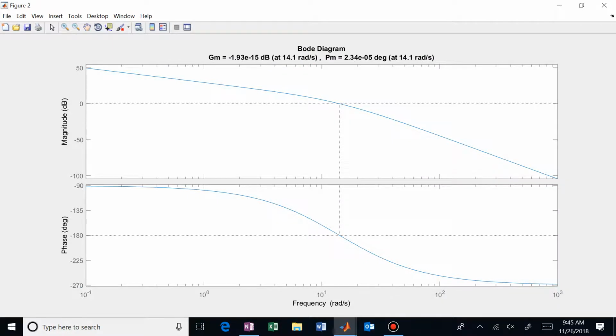And it actually gives me the gain margin and the phase margin. And if you look at this, you can see that, wow, you have a whopping gain margin, basically 0, and a phase margin of 0. And those are both occurring at the same frequency. So now this shift of omega sub g and omega sub p, or that difference between, doesn't even happen in this adjusted or uncompensated Bode plot.